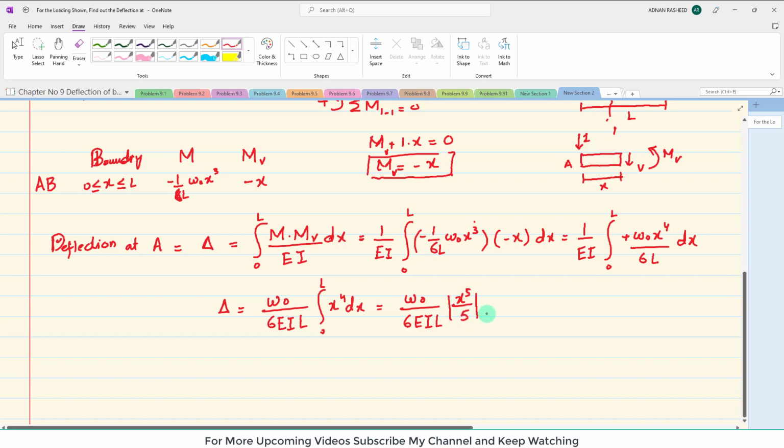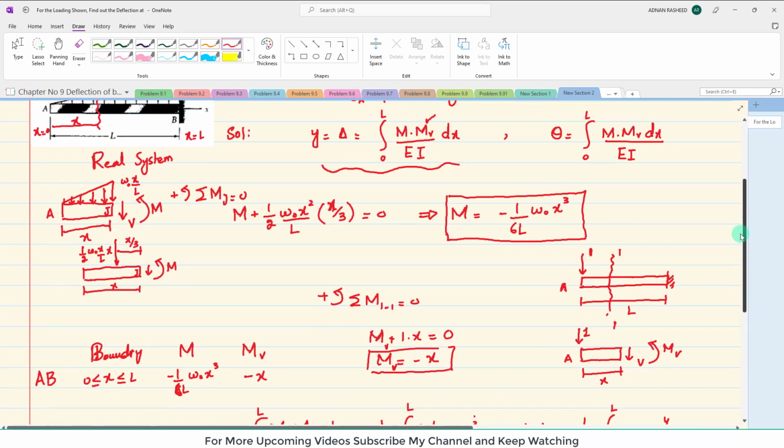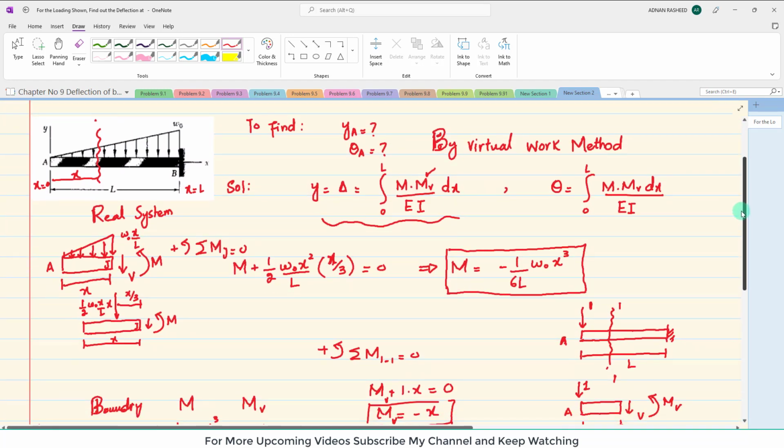And the limit will be from 0 to L. So if you put the limit, it will be W naught L^5 over 30 EI into L. Clear? So this delta or deflection at point A will be equal to W naught L^4 over 30 EI. So this is the deflection at point A. You can see this is the deflection at point A.